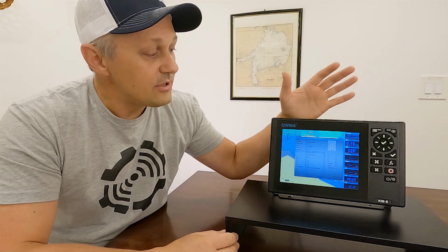There's three popular types of networks out there today. The first and the oldest and really the least used today is NMEA 0183. This has been replaced by NMEA 2000. Both of these networks are industry standard networks from NMEA. This will allow manufacturer A to work with manufacturer B and vice versa. So we can take a GPS antenna from manufacturer A, hook it up to an MFD from manufacturer B, and still have all the information that we would if they were from the same brand.